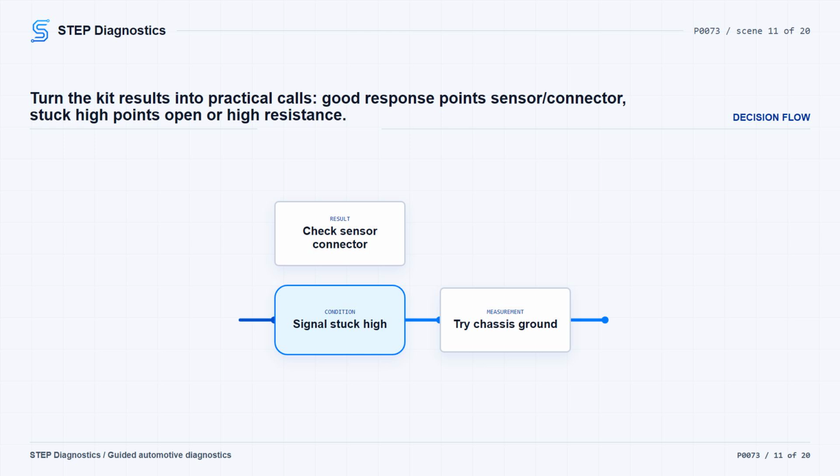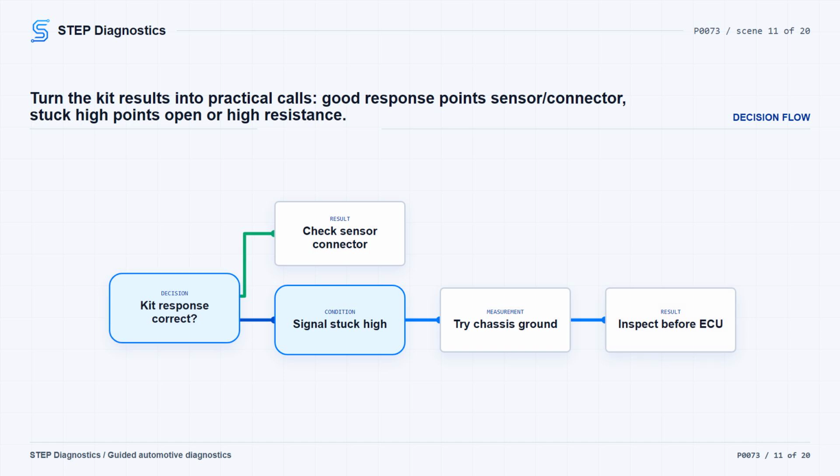If the signal is stuck high, or only the circuit high fault sets, think open circuit or very high resistance in either the temperature sensor signal circuit or the sensor ground circuit. With the tool switched closed, if the scan tool still shows voltage present, move the ground side test lead to a good chassis ground. If the voltage drops to 0.0 volts, the resistance is in the sensor ground circuit. If voltage is still present, the resistance is in the signal circuit. Check the correct circuit for high resistance. Typically, it should be less than 3.0 ohms.